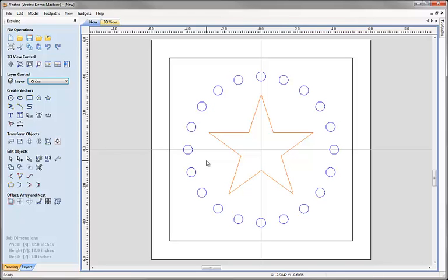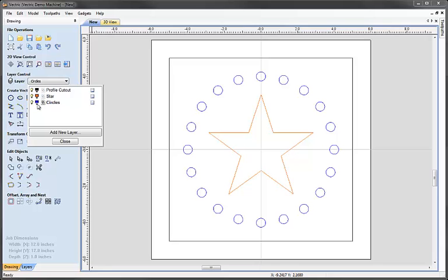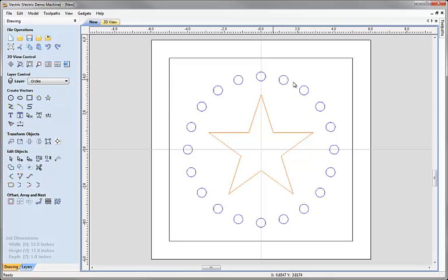they were one thing. Now you'll notice that all these circles are blue, and that's because my current active layer circles is blue, and so when we did that array command there, effectively that group we've created, which is a whole bunch of single vectors that have been grouped together by the software, has been created on that layer. So that group as a whole exists on that one layer. It would certainly be possible for me to ungroup it and assign these circles onto different layers if I wanted to. And we'll explore the idea of groups and layers a little bit more further along in this video.